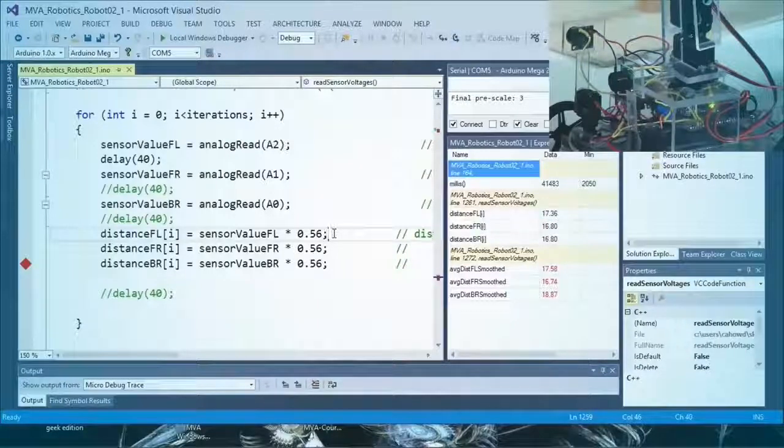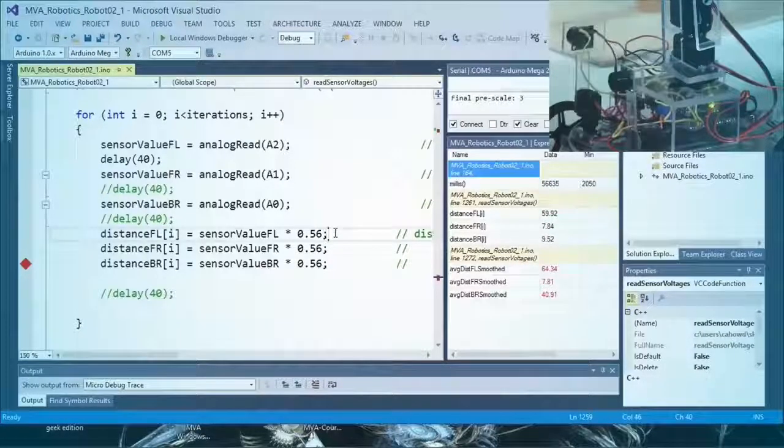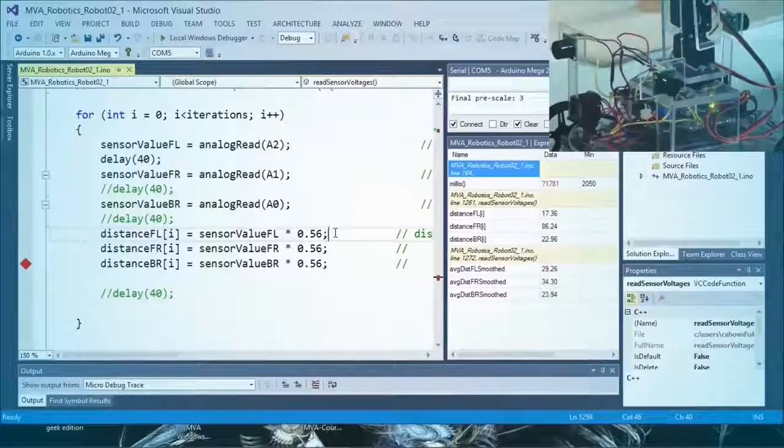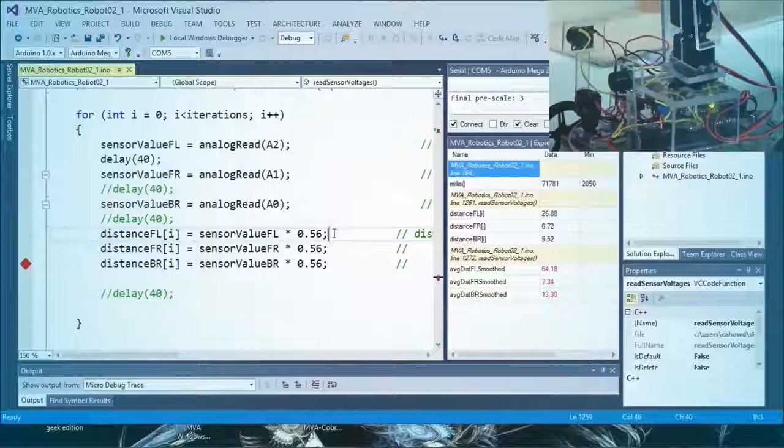Yeah, we're waiting for it to stop. After it stops, then we take readings. And it's just taking readings in the room here. And how many times is it reading per second? This particular sensor allows you to take readings every 30 milliseconds. And so we have 3 sensors, but we're firing all 3 of them every 30 milliseconds. And that's why there's so much variation within that time period that you're reading, and so you're just getting the average of those various readings.